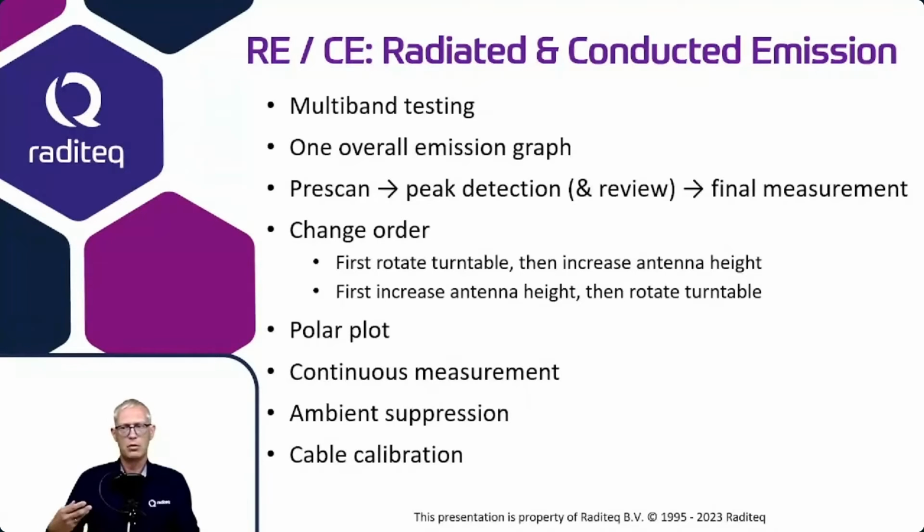If we're going to review some of the test setups that are available, we start with radiated and conducted emission. We call it RE and CE for radiated emission and conducted emission. And one of the concepts that we have now is that we have multi-band testing. And in the test configuration, you can define one band, which is just a frequency band from the start frequency to the stop frequency.